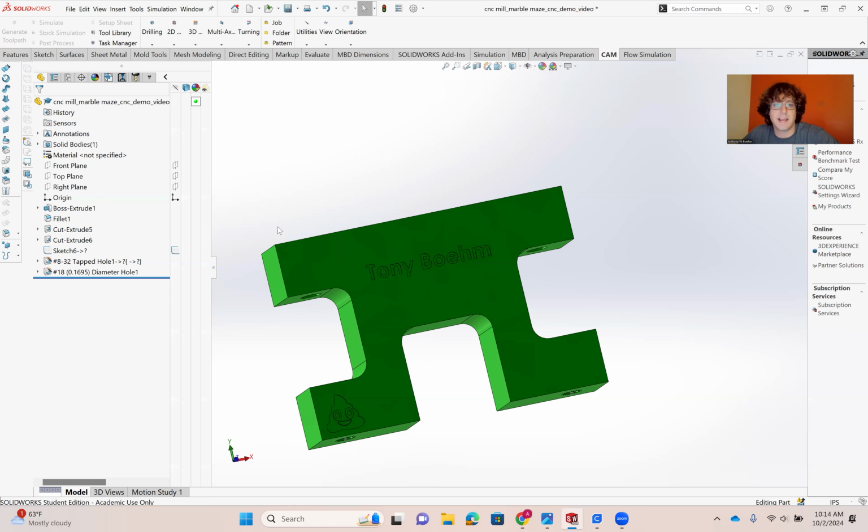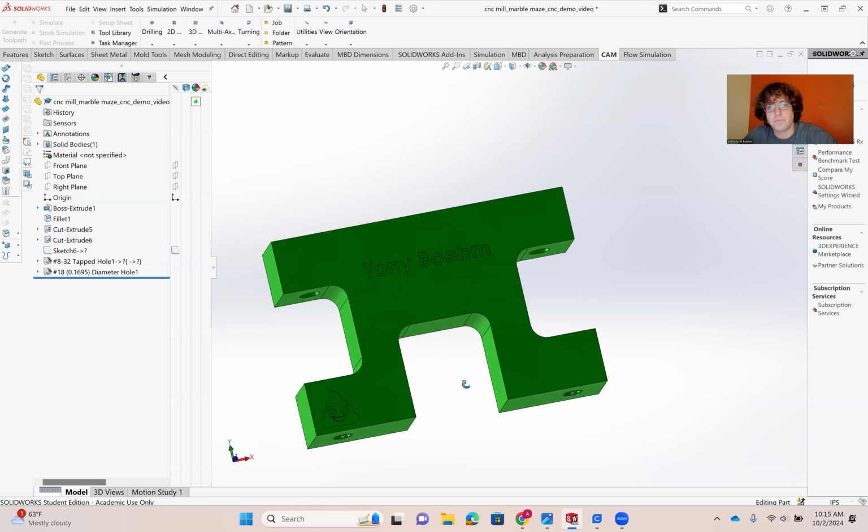Okay, so let's say I got a piece of material that was exactly as wide as this part here. I could grab it on one side and mill this pocket, and then grab it from another side and mill this pocket and so on. But if I had it in the vise, whatever direction I had it in, I would not be able to cut the contour that touches it. And we also want the tops and bottoms and all sides to be machined relatively well. Okay. So that's what we're gonna do.